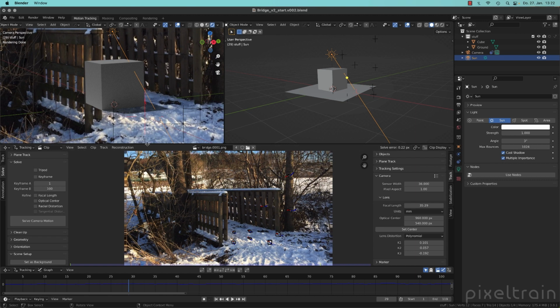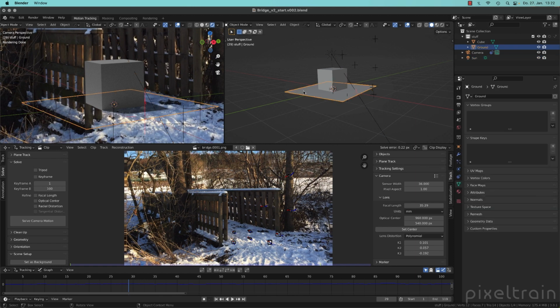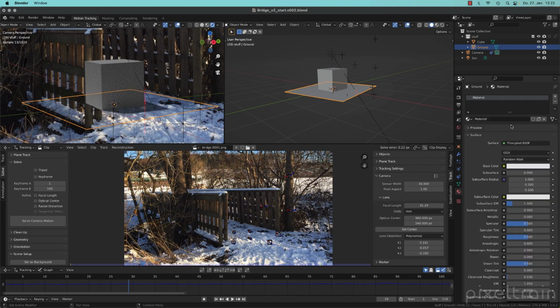A shadow catcher really interacts with your objects. And this is something I want to demonstrate now. You see here the cube has a really neutral reflection. Nothing is going on here and the shadow is perfect. Let's select this plane, which is not visible at the moment. Interesting. We go into the materials and make a new material and we say this is our shadow ground plane, whatever.